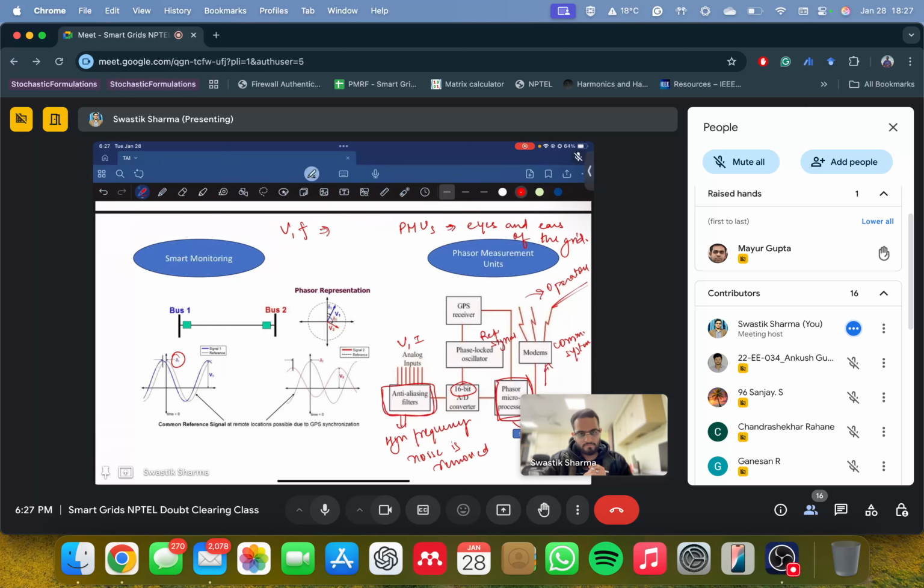But there are already protection relays in place, which will take care of all the protections locally. In all the bays there would be, if not differential, distance protection and all those fast tripping schemes. So why would I want to isolate it sitting in Delhi with a PMU? Protection systems are very reliable, we have been using them for years, and there are redundant relays and all those things. Why would I want to use a PMU to isolate from a remote location?